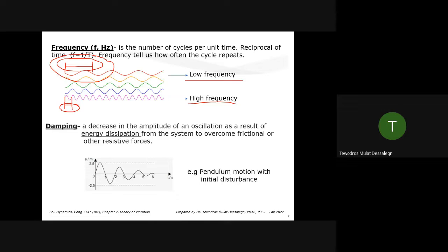Buildings from 5 to 15 stories were selectively damaged because their period closely matched the period of the soil and the amplified motion. So this is a big concept, just be aware of it.